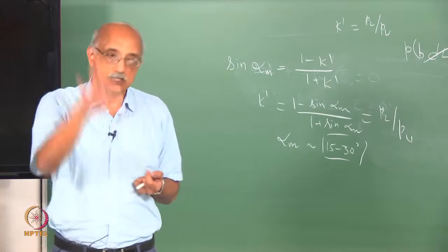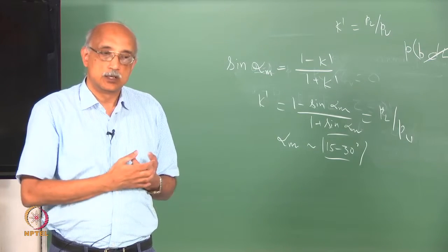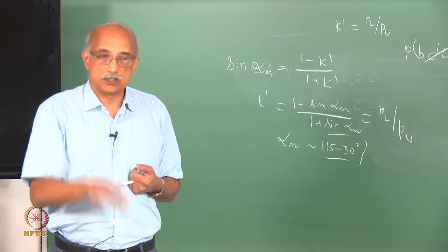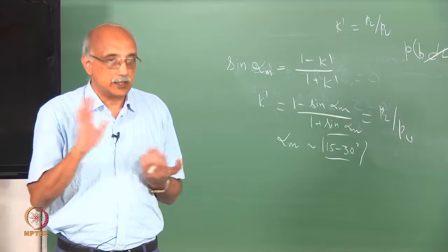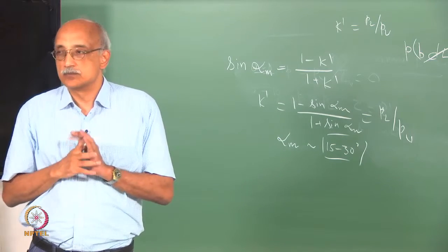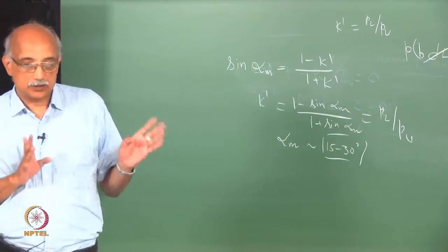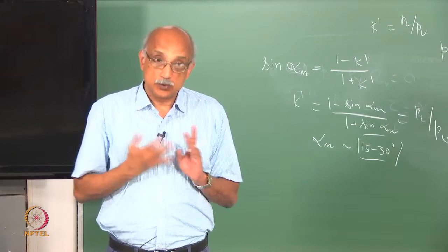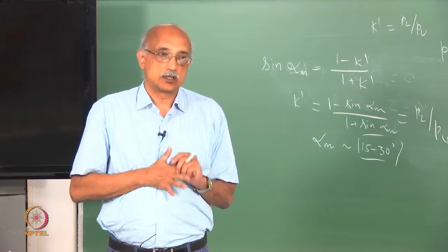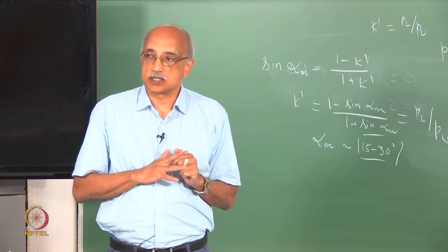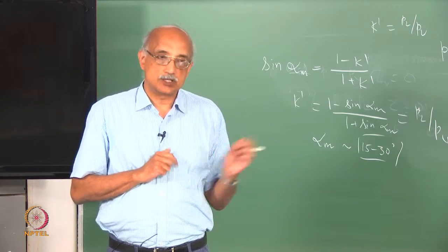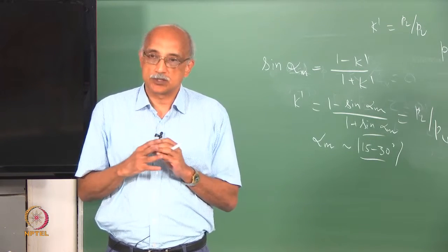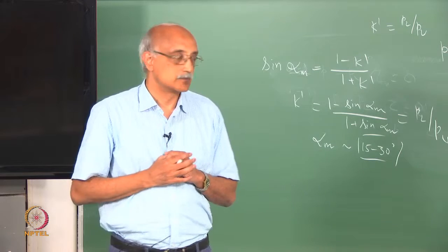So, the streamline is essentially a vertical downflow, but the density can vary quite significantly along this direction of flow, which violates the principle of incompressible flow. So, many of the theories that you may have already read or you will be reading about fluid mechanics rely upon incompressible flow characteristics, and that is another major difference between particulate mass storage and flow compared to liquid storage and flow.